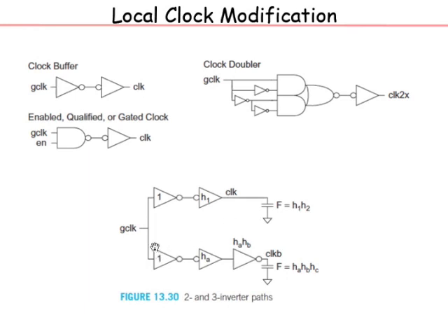So you have the global clock, you have maybe an even number of inverters to get my clock and an odd number to get my clock bar, but you still need to match the delays. Okay, and that you can match by adjusting the sizing out here. Just like when we discussed the SRAM timing generation, I said you look at the pull-ups and pull-downs and you match the two and so on.